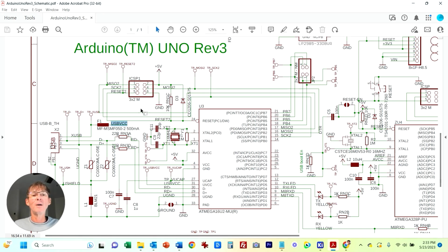That should never happen unless there's some type of voltage overspike, ESD, that type of thing. So this diode will basically prevent the reset line from going more than a diode drop above the 5 volts, so it should prevent it from causing any damage. Then we just have, let me see, it looks like a pull-up resistor here on the reset line.